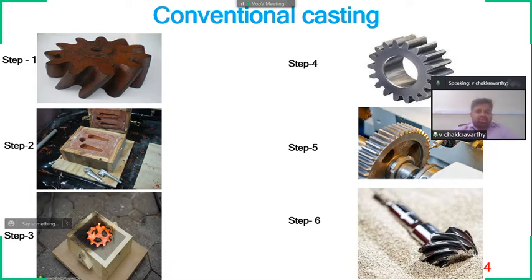Okay, so if we are preparing a pattern and removing a lot of material, then material wastage is one more way of incurring a lot of cost, a lot of fabrication cost. But in the other way, we have to think about the increased tooling cost also that will be there. So these together constitute a very huge amount to the end customers, and it will affect the affordability limit.